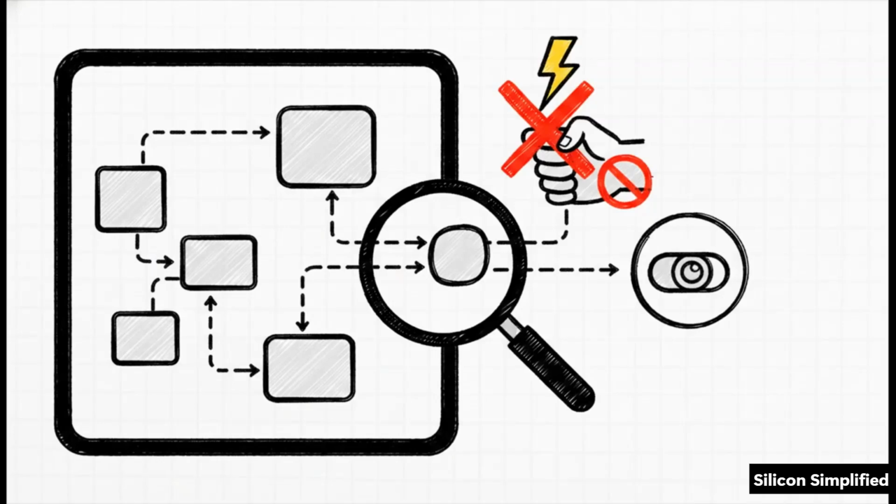Now you might be wondering, why does this matter so much? Well, when you scale up from block-level testing to full system-level testing, you absolutely need passive agents to observe internal compliance without accidentally overriding live signals. At the block level, sure, you use an active agent to drive a standalone IP block. But when you integrate that block into a massive SoC, that interface is now physically wired to another block inside the chip. You can't actively drive it from the test bench anymore without causing a massive collision. But you still need to monitor it to make sure the protocol is behaving, right? So you literally just flip a configuration switch, the agent becomes passive, and boom, your verification logic scales perfectly.